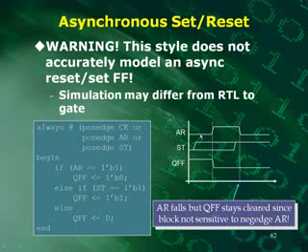So let's say while this asynchronous reset is high, an asynchronous set comes along and goes high during this time that this is high. When it goes high, that's the positive edge of ST, it comes in here. But we've said that if the asynchronous reset is 1, then it just keeps it low. So nothing actually changes. The Q flip-flop still stays low.